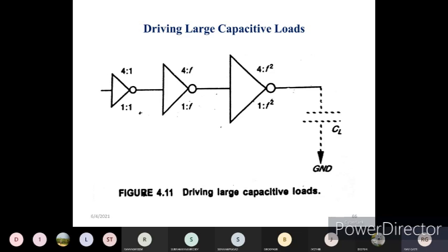We have just now measured the area capacitance. When the entire circuit of the chip is off chip, the capacitance of the entire system should generally be high when compared to the capacitance of the on chip cases. This we call the load capacitance. This capacitance should pass through a low resistance value, otherwise a longer delay will occur in the entire IC circuit.